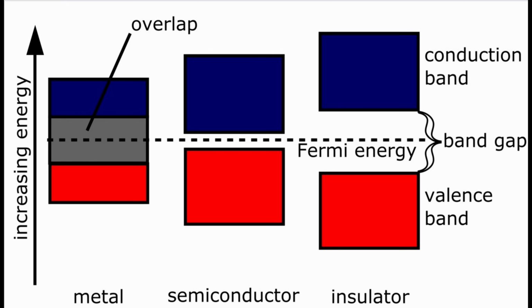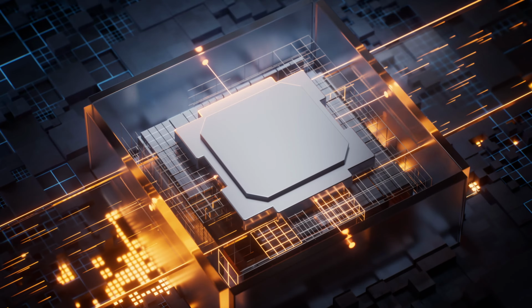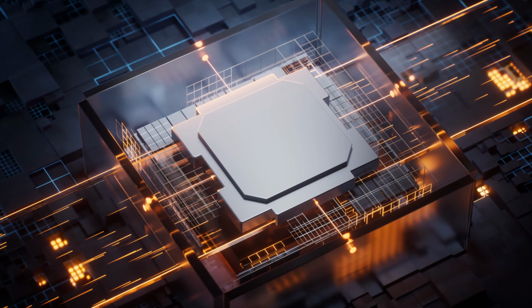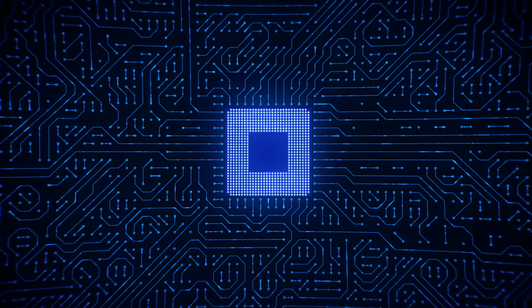The size of the band gap is what differentiates conductors, semiconductors, and insulators. The band gap is the minimum amount of energy required to excite an electron from the valence band to the conduction band. When a semiconductor gets energy at least equal to the band gap, the electron is excited to a free state, which can now participate in conduction. A hole is also formed at the spot where the electron was previously present. This hole also plays a role in conduction.